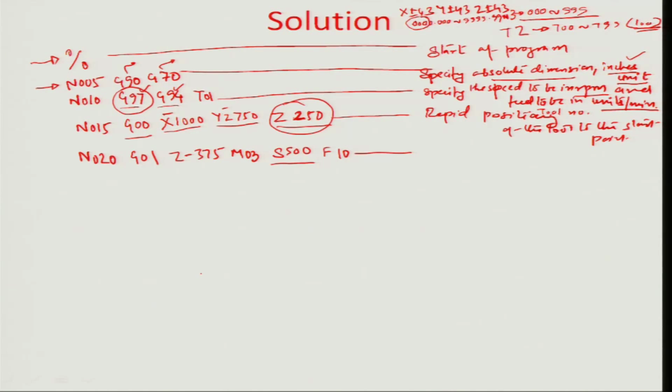the whole command block. And so this command block basically indicates what all? It turns on the spindle, it feeds the tool to the required depth, at the feed rate indicated, and then it turns on the spindle at a certain speed and lets it go up to the 500 RPM speed.